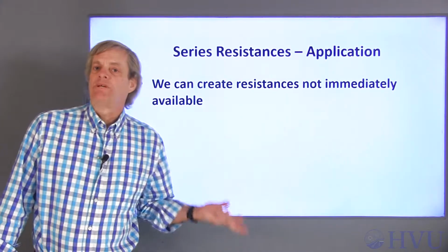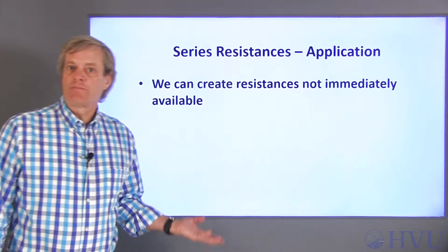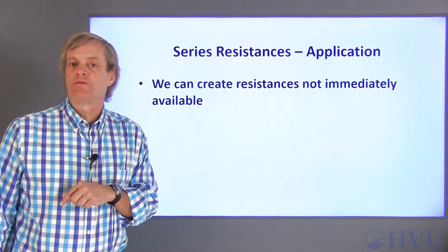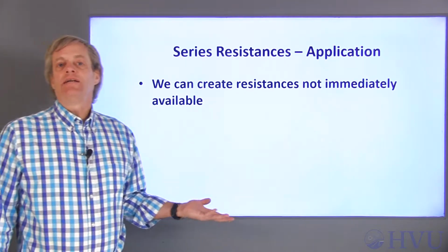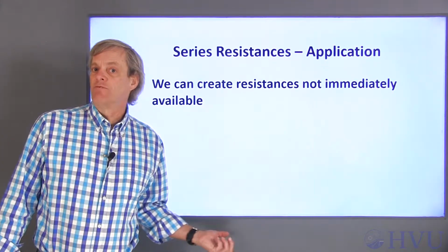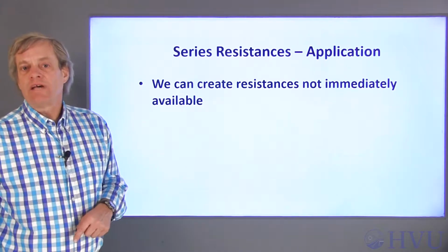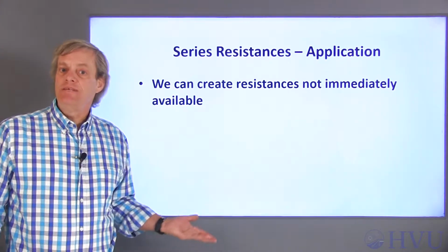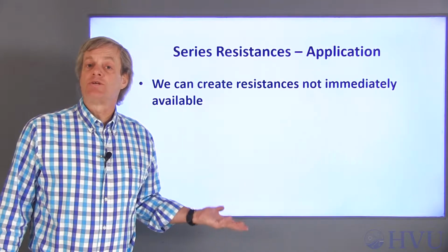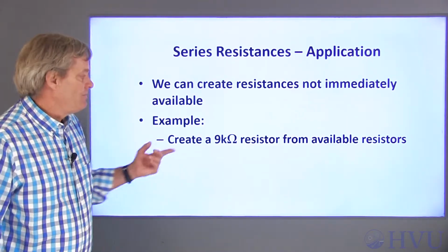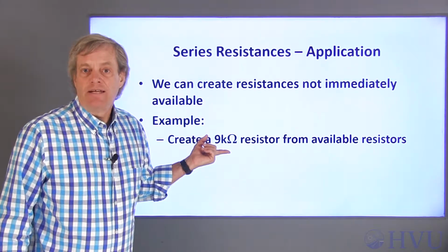I'm going to do KCL at this node to determine this current I. We're given 3 other currents with their assumed positive direction and a numerical value. So negative 1 amp here simply means that 1 amp is going in the opposite direction. So if I assume positive currents leaving, 4 amps is entering, I have to change its sign.